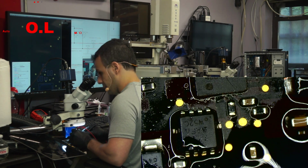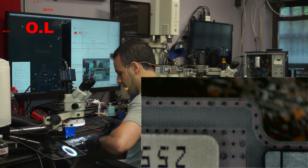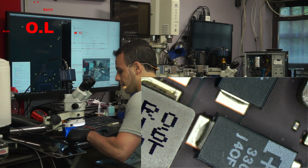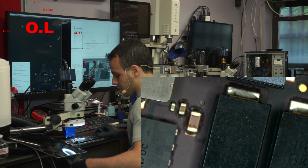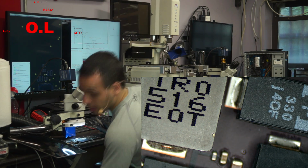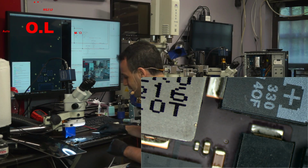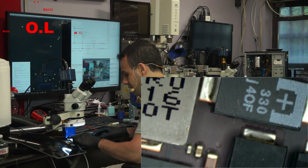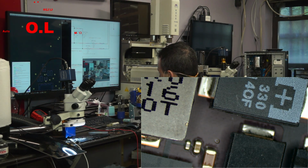Okay. Now, what's interesting is that cap. I wonder if that cap having a solder ball there was actually a short. I wonder if you short that line to ground, if it actually kills the LED driver. Because that's the only thing I can imagine, because even after I removed it, my short was still there. And that little filter cap had a solder blob next to it. So I'm not going to say that that cap is totally innocent here. That cap may have been killing my LED drivers.